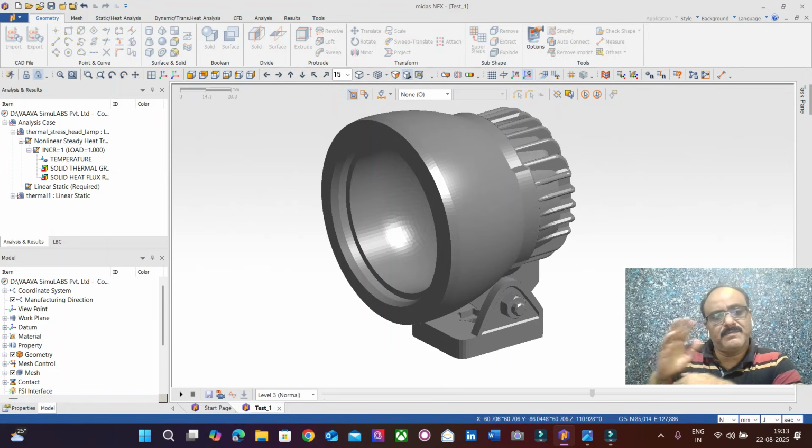Okay, so when we perform a dynamic simulation for a structure, what we do is we change the parameters with respect to time. So the loading can be varied with respect to time. Okay, it can be a point load, it can be a rolling load, or it can be a shaft load, it can be a wind load, it can be an earthquake load. Okay, any kinds of loads. Okay, when it is varying with respect to time t, that will be called a transient simulation.